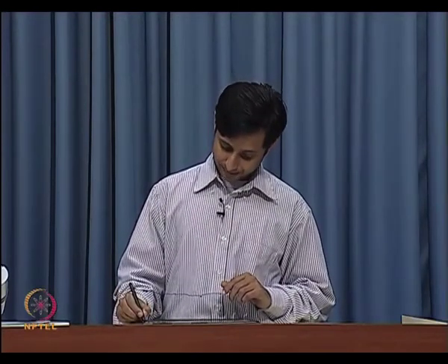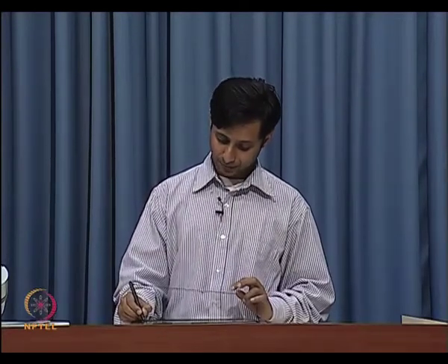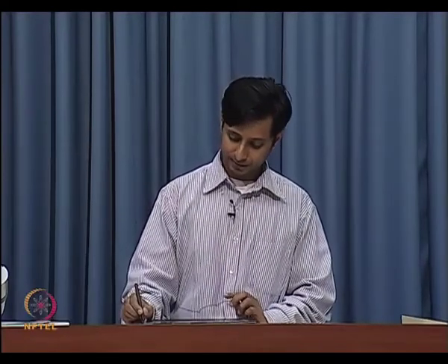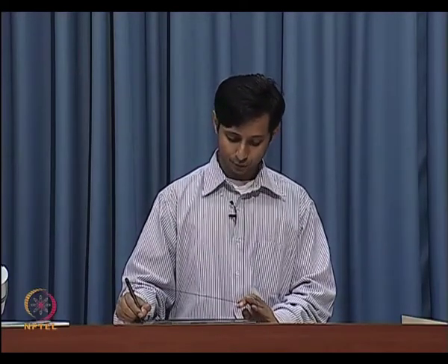The next step, we discussed input referred noise. We did a small problem to solve for input referred noise. We showed how we can refer the channel noise back to the gate and make life easier as far as our problem solving is concerned. Then we discussed a few definitions: noise factor, noise figure and noise temperature. All of these try to tell you the performance of the system in comparison to the noise already available from the source.